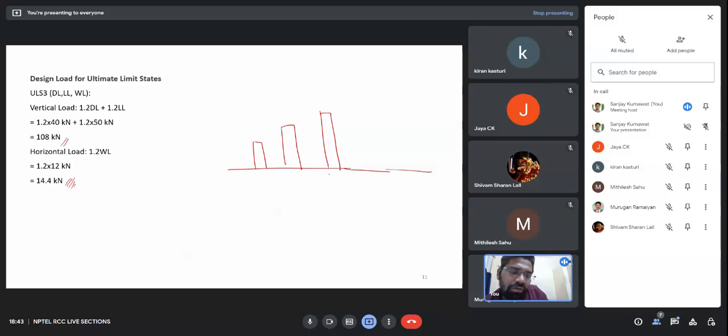Okay, so now an earthquake has come and these three buildings are subjected to some shaking. Now what will happen? I will have some different frequencies of this shaking, for example, omega 1, omega 2, and omega 3. Now, for example, this building has some time period, this building has some time period. So depending upon the different time periods, these buildings will respond differently to different frequencies of the earthquake.